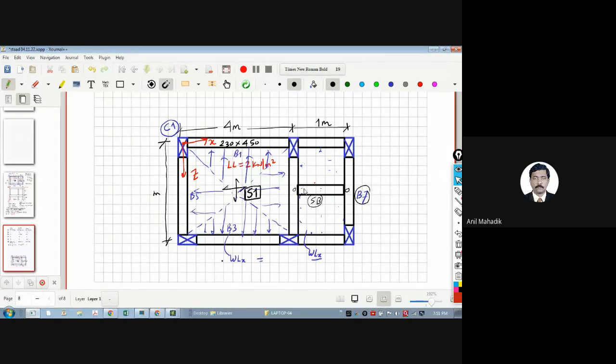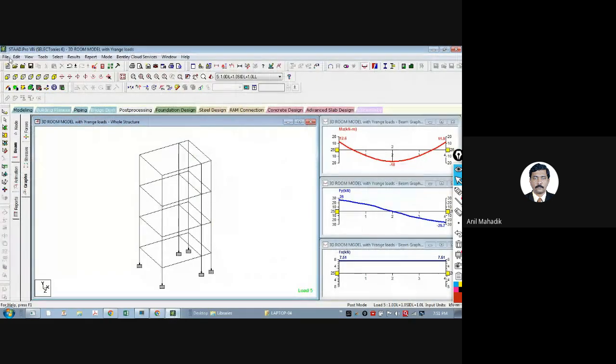So this should be a simply supported beam, and when there is a simply supported beam, that means the bending moment is like this, which is WL square by 8. So moment is 0 at the ends, right? Now software doesn't understand whether you are saying it is simply supported or fixed. It is taking by default fixed condition in any software. If you want to forcefully tell it to make it simply supported, then there is a command for this. I will tell you. Now let's model this beam first.